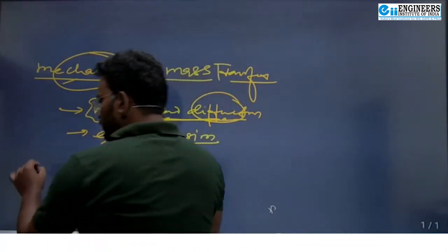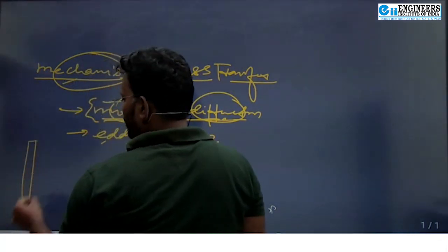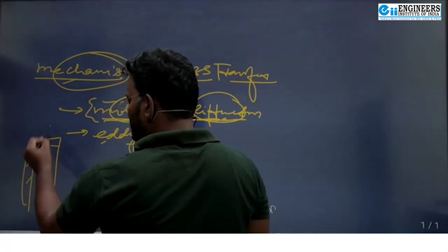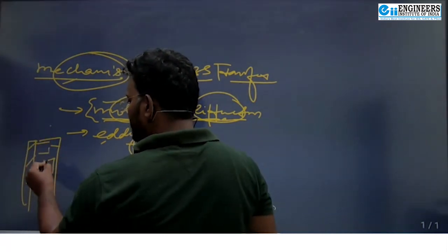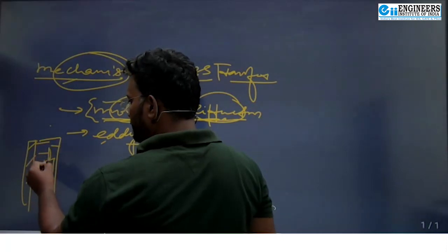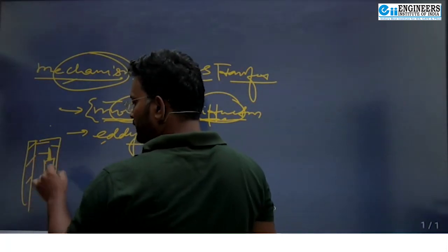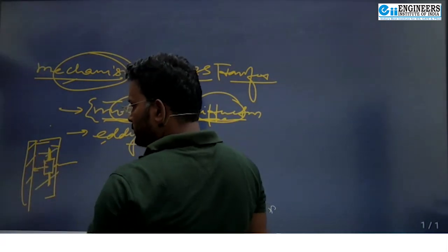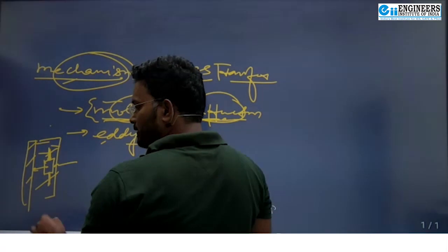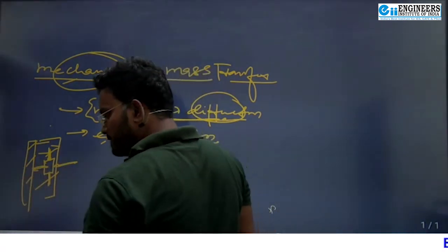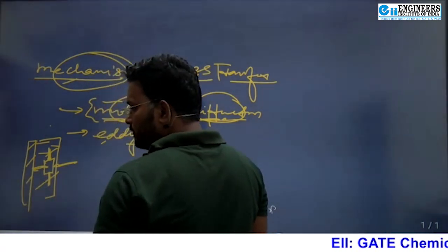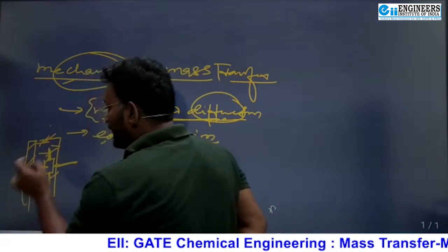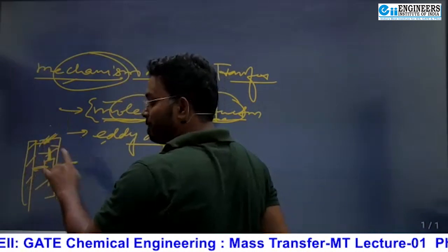Remember? Recall, this is the plate and this is the fluid, the fluid is flowing over this plate, over the plate we took an element here, and we have assumed a differential element. Here the momentum transfer is due to bulk advection, and this is by molecular diffusion. So this effect has been cancelled out because velocity is the same in the x direction. Then only momentum transfer is by molecular momentum transfer. Am I right? So momentum can be transferred, and that was only in the laminar flow. Am I right? That was the discussion we did only in laminar flow, not in turbulent flow.